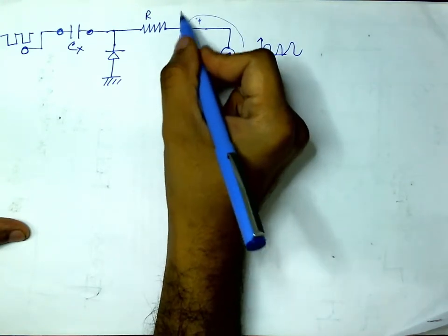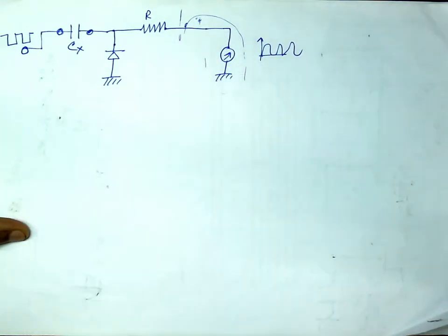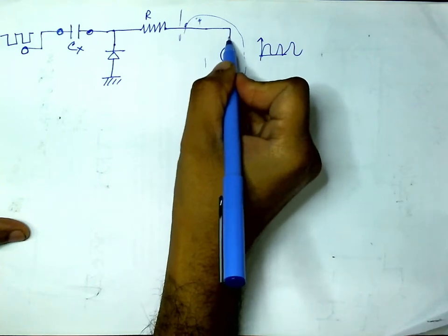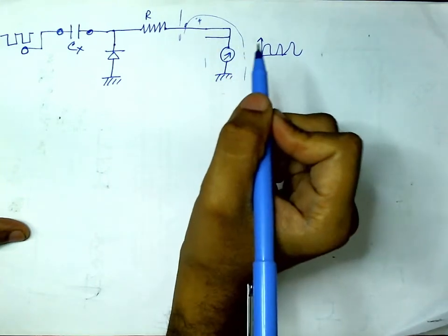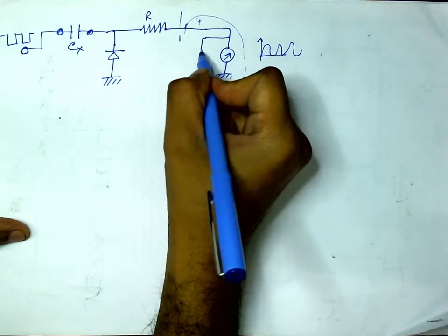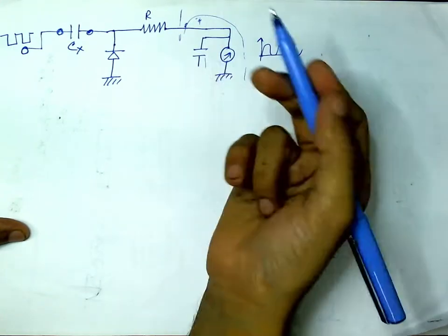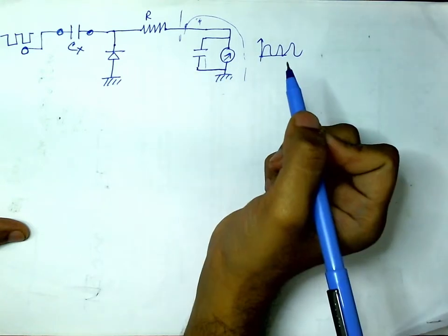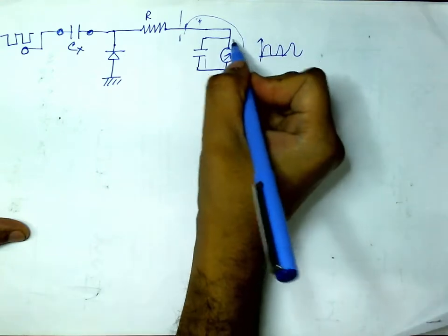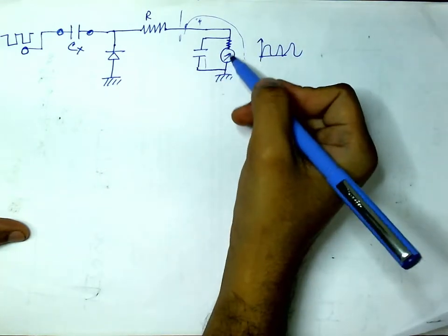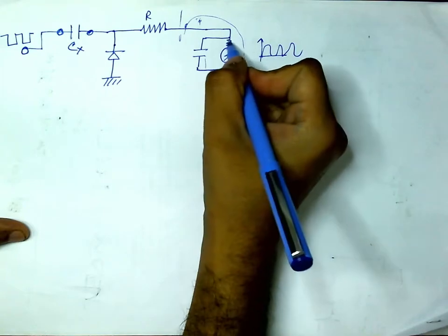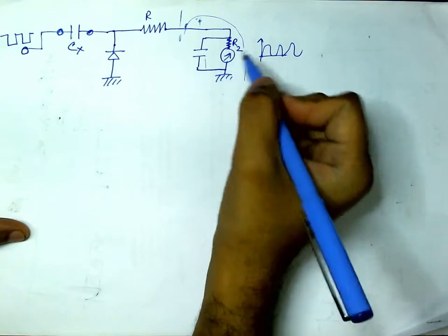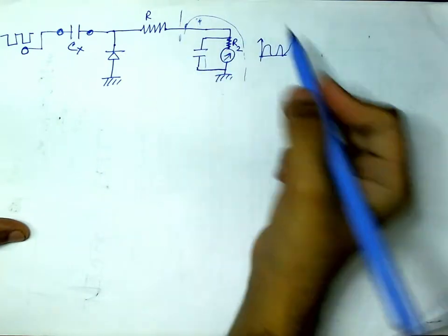So this part, after this resistance, I will give a shunt, basically a parallel thing, which is this. And here I will have some resistance. If the meter resistance is not enough, I can put some more resistance, call it R2, extra resistance. I'm telling you why.